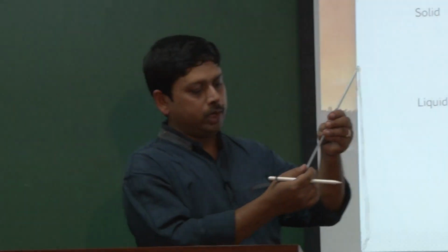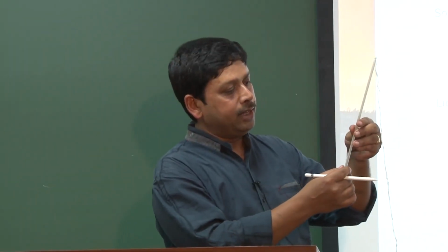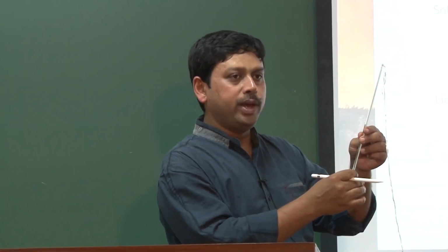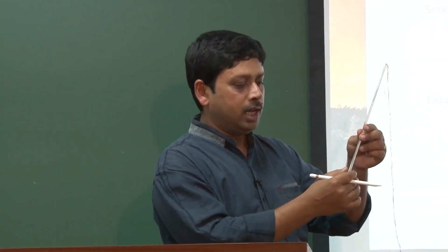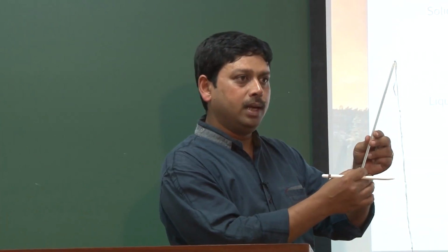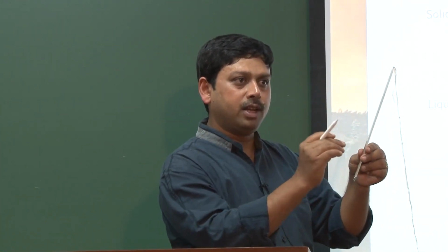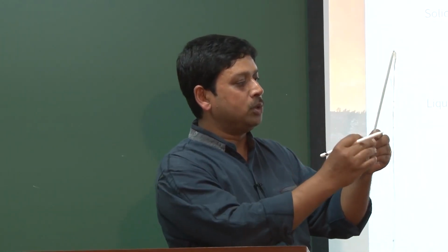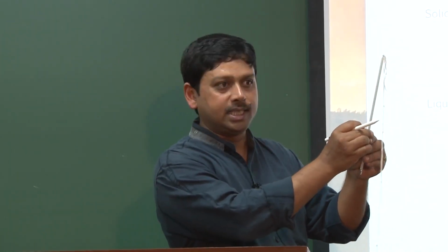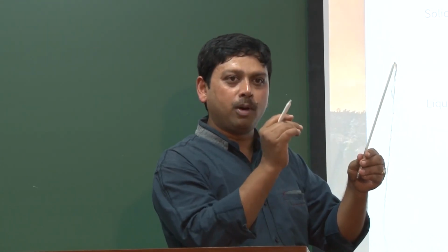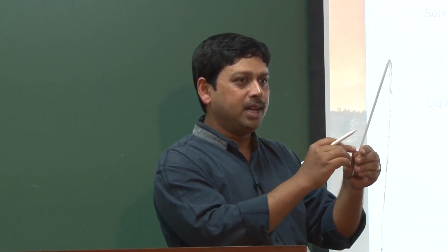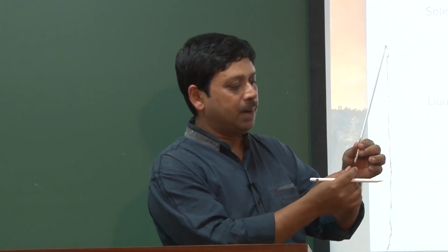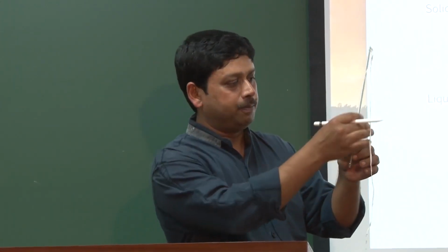here in this particular volume, and then there is a small capillary, a very thin and narrow tube through which the volume can expand. Because of the smaller cross-sectional area of the capillary, the change in length for a given amount of volume will be much larger, and on top of that there is a prism to magnify what is inside. So, this very small amount of expansion in the liquid can now be observed when you put it in this particular setup to measure that.